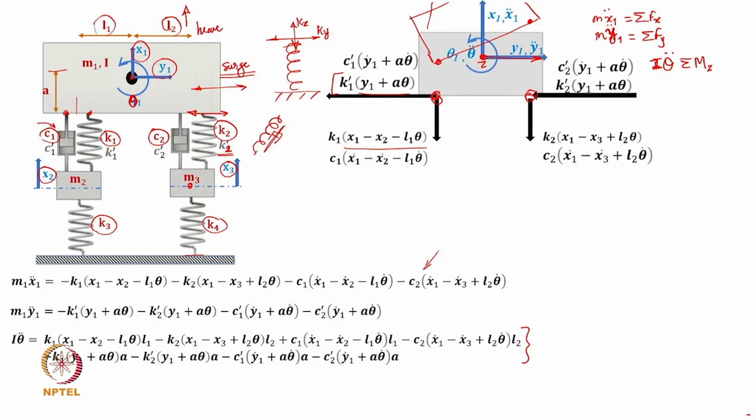So, if we assume this free body to be moving, it would be moving in its positive direction of all the degrees of freedom, and when it moves from its original mean equilibrium position, what are the displacements in the connection springs as well as dashpots is something which you can find out yourself, and that is something which will give you the restoring forces at both these two connection points from the two suspensions, as well as the dissipating forces generated in the dashpot of the suspension.